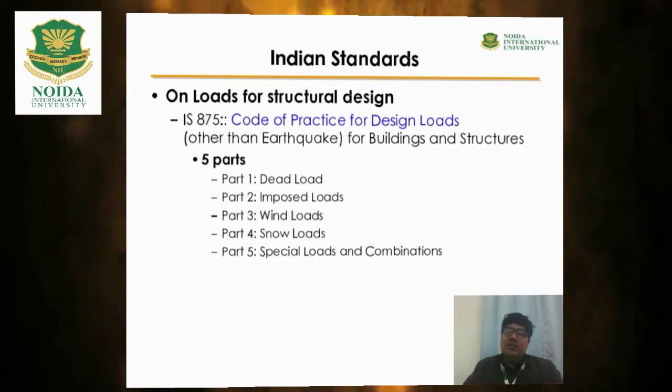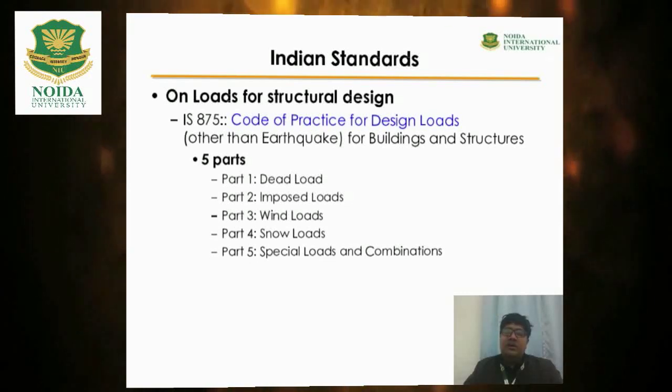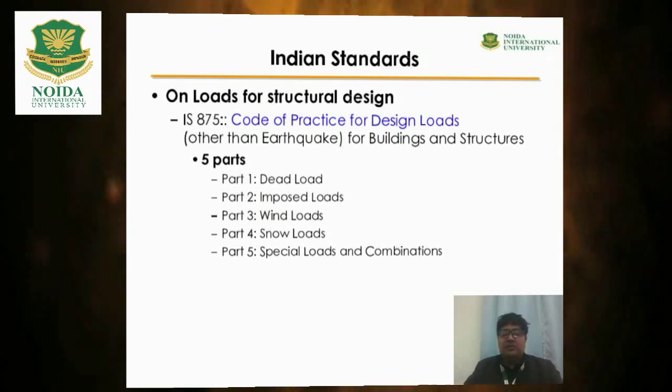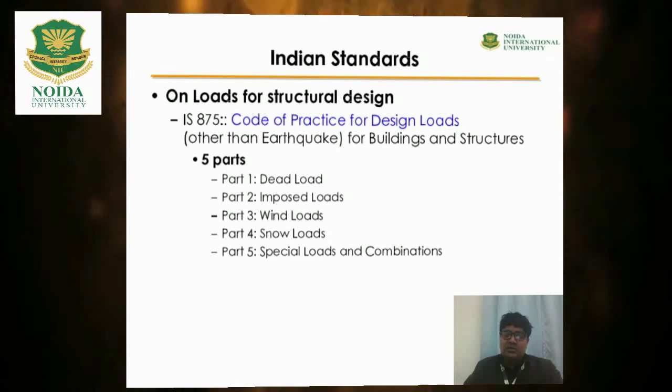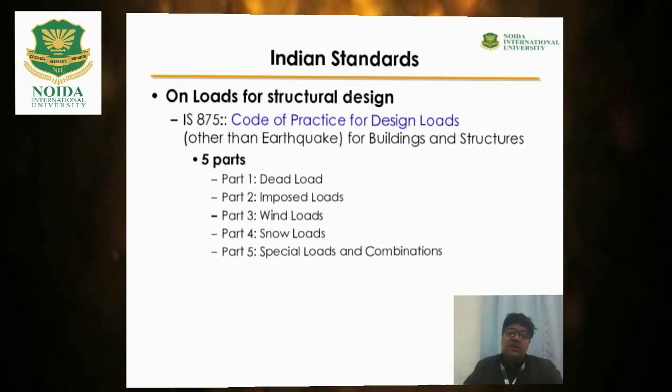As per the Indian Standard IS codes, there is IS 875, which tells you about the code of practice for design loads. That code of practice is divided into 5 parts. These are the different kinds of load which are imposed on the particular structure, and these loads do not include the earthquake load. The earthquake load is calculated as per a different IS code, which is IS 1893 for buildings and structures. These loads are just for buildings and different kinds of structures.